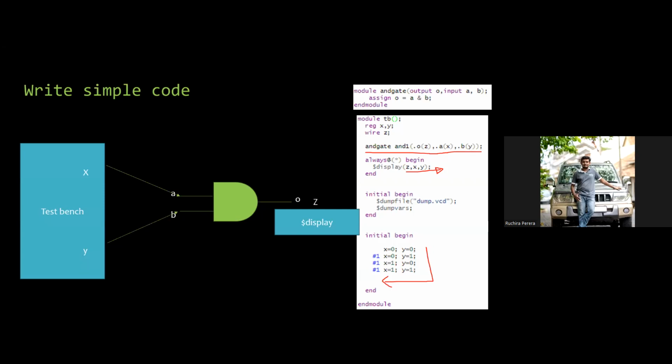So this is not the only way of introducing the AND gate. Even you don't need to introduce AND gate in Verilog. You have predefined AND gates available, but I just did one for demonstration purposes. Even you can write complex Verilog codes here, so that will modify this circuit, and basically you can write multiple gates, multiple files. You can import multiple files to a single test bench, and then compile and simulate. So you can do a lot of things.